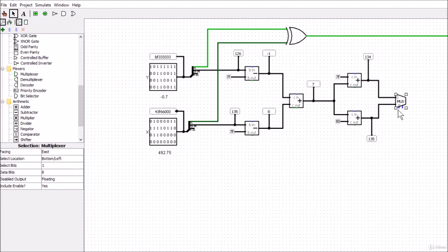Now there's going to be a choice as well that's going to be made for this multiplexer. So the choice is going to come out here, and we'll just take the choice along here, and it's going to have to come in. So the value for this choice is going to come from the 48th bit of the multiplication. But we've not done the multiplication section yet, so we can just leave this hanging for the moment. But we're going to have an output here then, and we can again put another probe at the output, and we won't have a value in it at the moment because the multiplexer isn't connected.